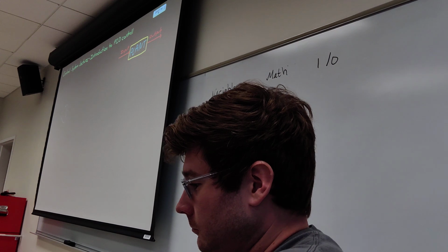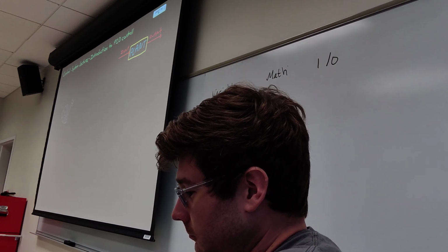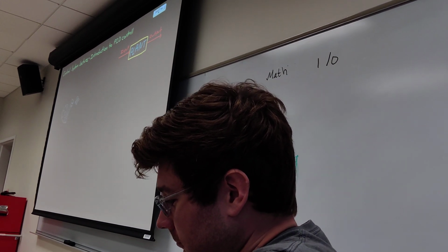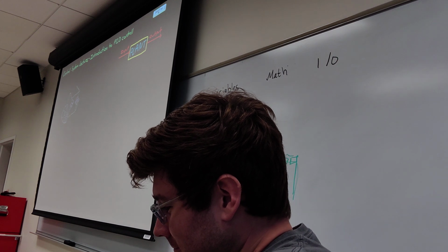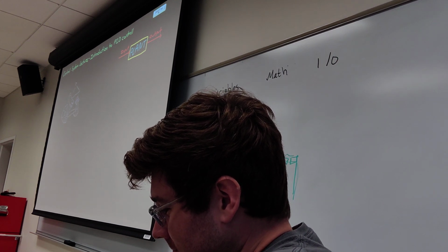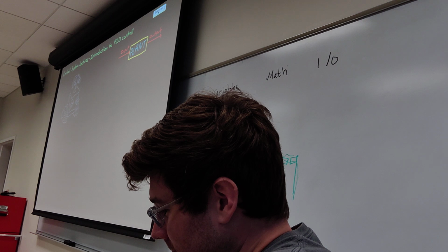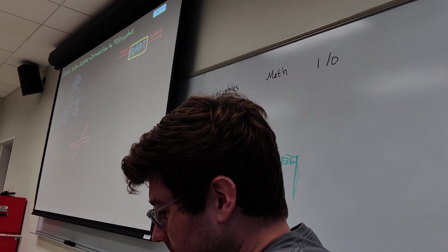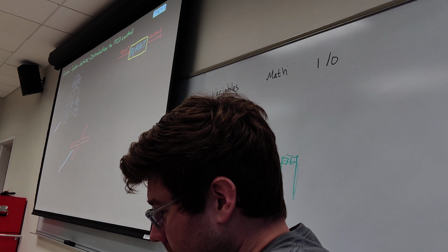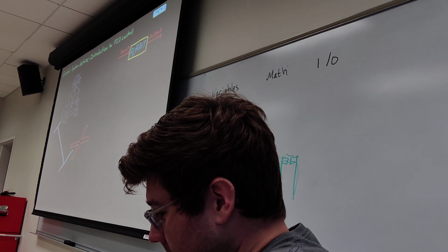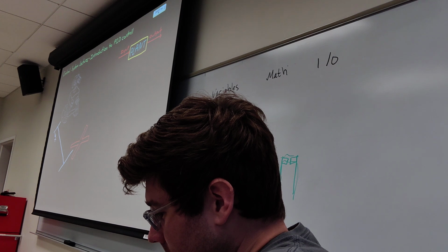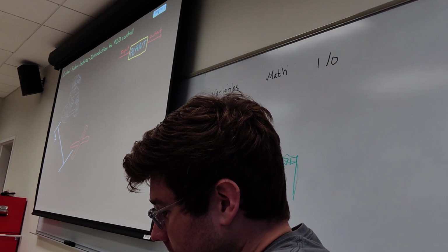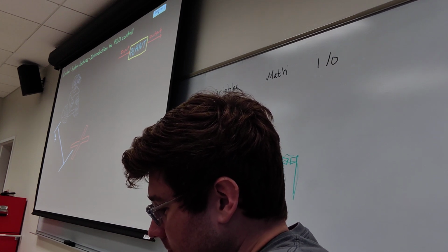Often in these open-loop scenarios, the performance of the system isn't good enough to meet your requirements. Let me give you an example of what I mean. You're tasked to build a robot that needs to move from this spot here over to this red X. You could figure out how fast the robot moves, and then from that determine how long the robot needs to drive for before it gets to the red X. This type of commanding is called open loop, because the amount of time the robot drives is not adjusted based on the actual position of the robot.